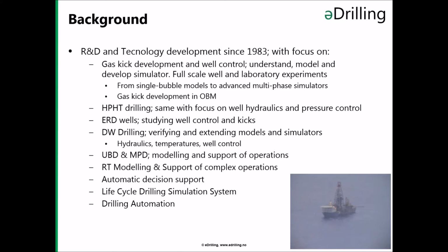So when I started, the single bubble models for gas percolation and rising were more or less the accepted industry standard, and now we have moved a long way over to accepting that the world is much more complex than this, and also that the realities of the process are implemented and reflected in the multi-phase simulators, which we now use for well control simulation.